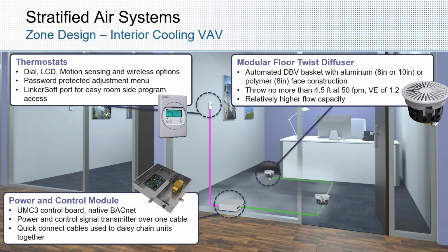So again, like you had seen in the flexibility video, talking about the adjustments in the space, here we can see the automated diffusers. So there's opportunity to make each one of these diffusers automated. That way, for intermittently loaded spaces, like an office space or a conference room, you can have those completely shut off and sealed up. And those can all be driven by the thermostatic control in the space.